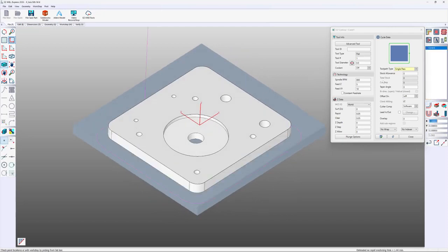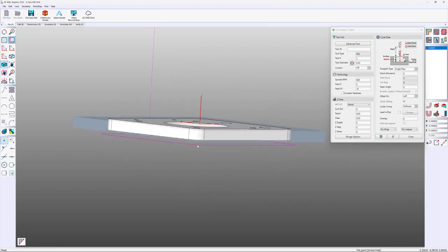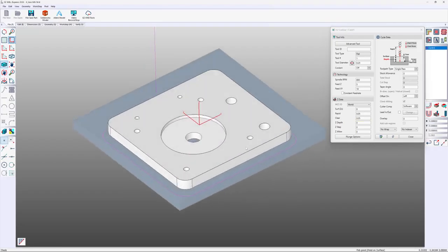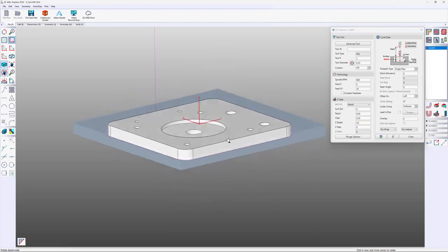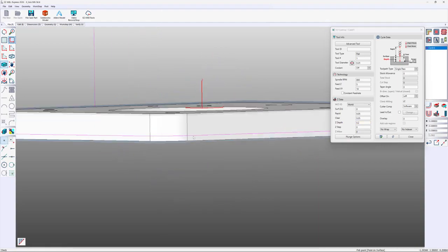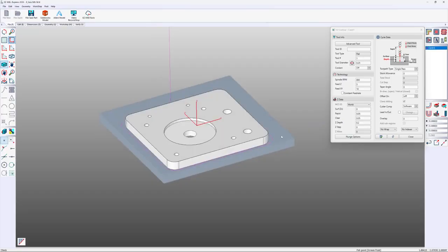So if I verify, let's change our cutter diameter to 1/4 of an inch. Depth is 0. Now because these surfaces are through with no floor, it gives us an additional depth so that we cut that completely. Let's leave a 50 thousandths height of our tabs. So I'll go with 0.2 inches. You can see that we're stopping. Now maybe 200 thousandths is a lot of material to take at once. So let's add a step of 50 thousandths.